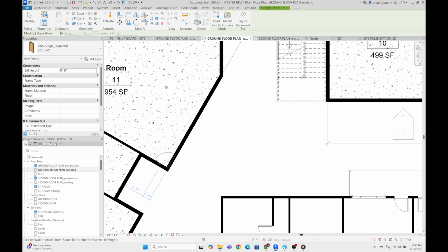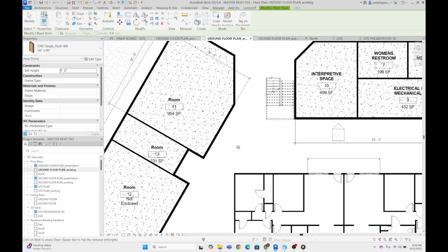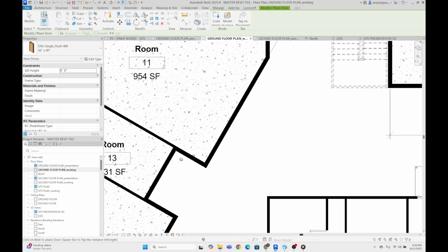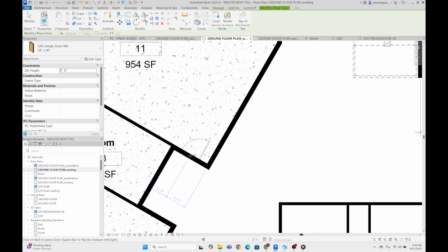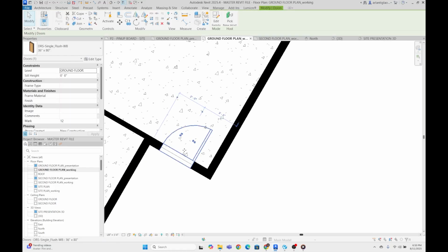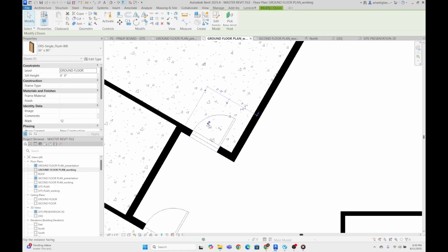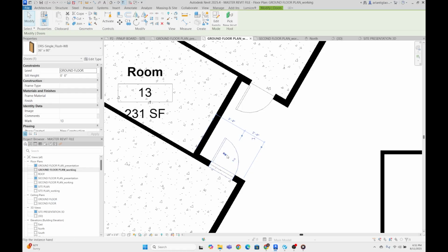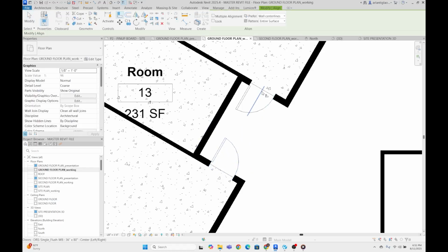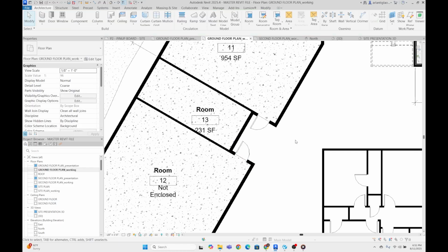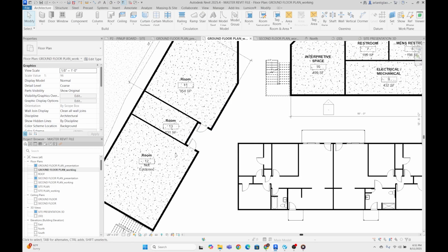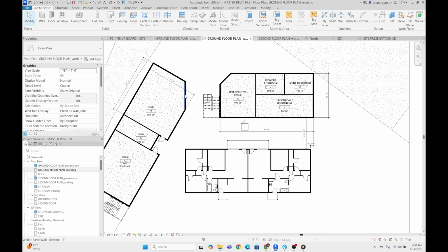just to keep it uniform. And if you notice, it latches onto a wall, and you can just click and place it, which makes it very convenient. You can change the direction of the swing by clicking on these arrows here. So I'm going to make them outswing and even use the align tool to make them straight together. And you can see that these doors are placed in.